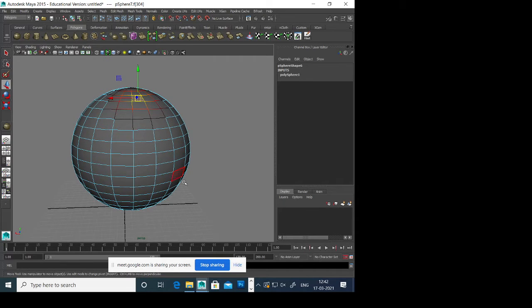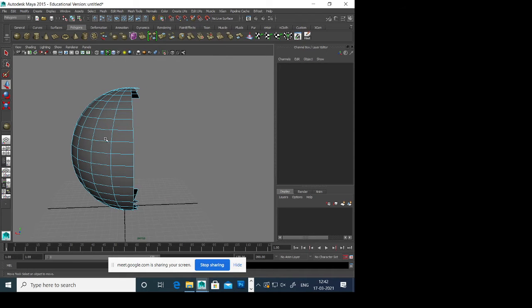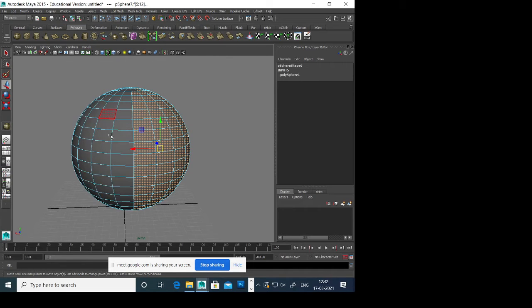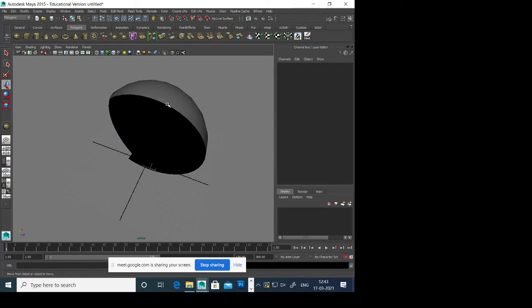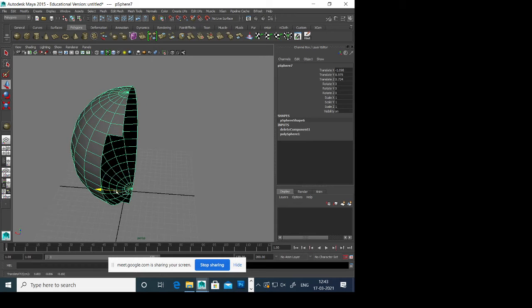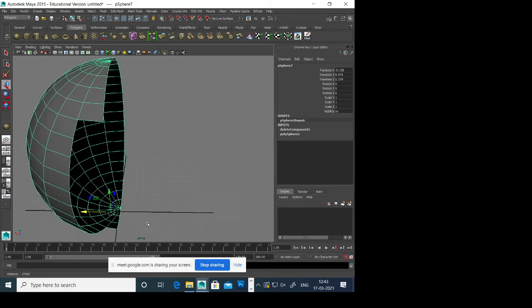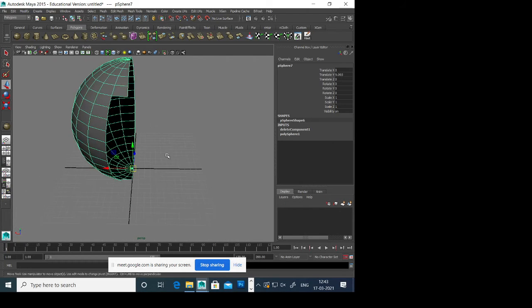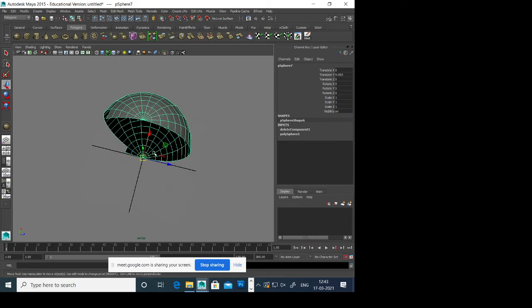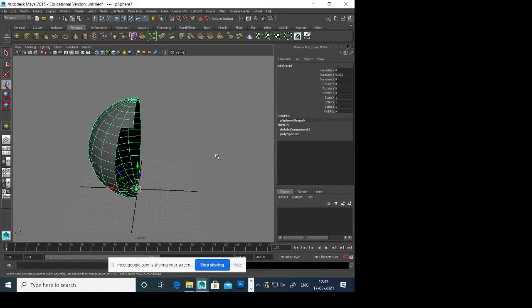Suppose you have this model, switch off your vertex. I just right click, face. I didn't even look, just did this, and selected this directly. So it selects, delete something, and suppose I want to create a symmetry of this model. So what I do is, whatever your pivot point is, based on that, it will create symmetry. So you have this position, world origin 0 0 0, Control D to duplicate the model, and this is your X direction.